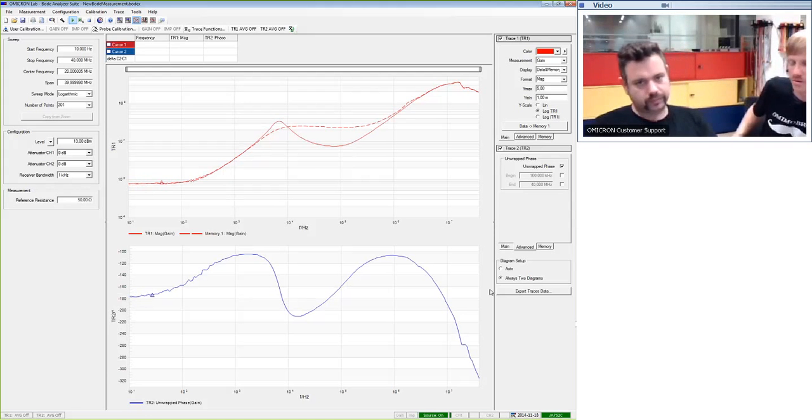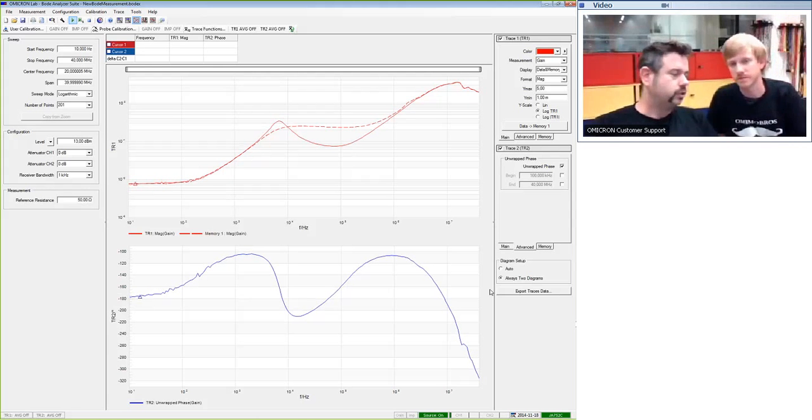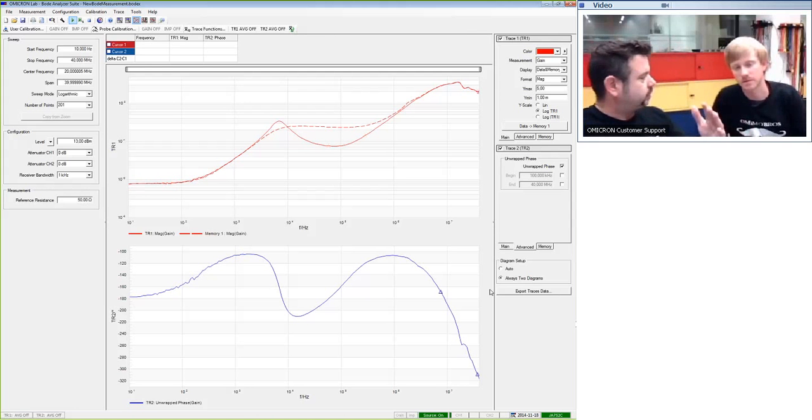But before you were mentioning this QTG. Yes, the QTG we require to derive the phase margin from the output impedance measurement. You know that the TG is the first derivative of the phase, so it tells me how steep the phase curve is at a specific point.